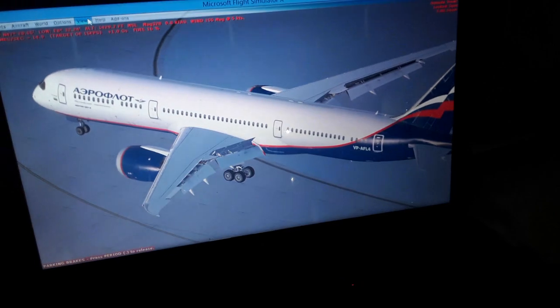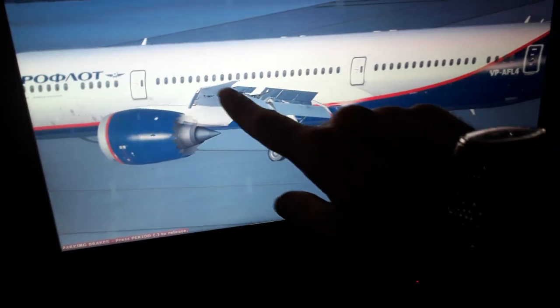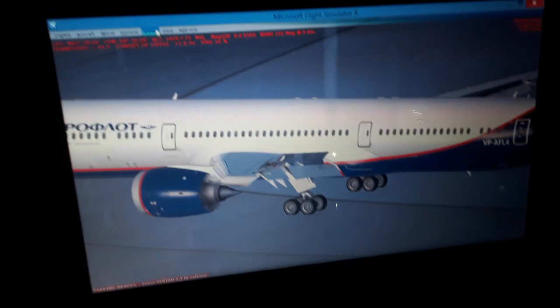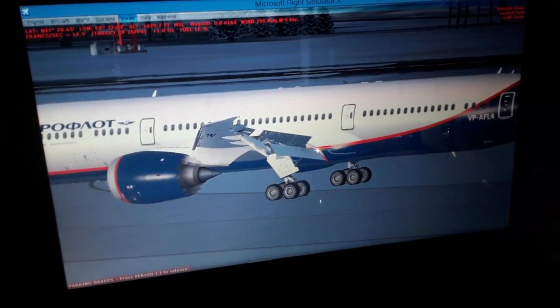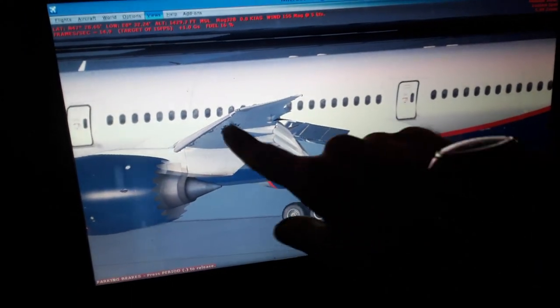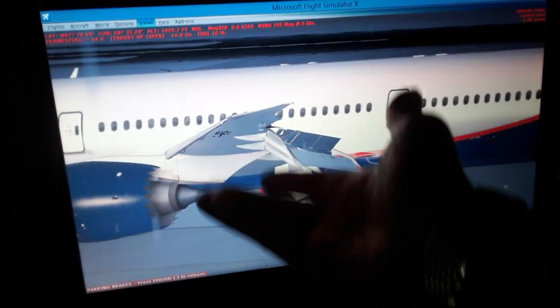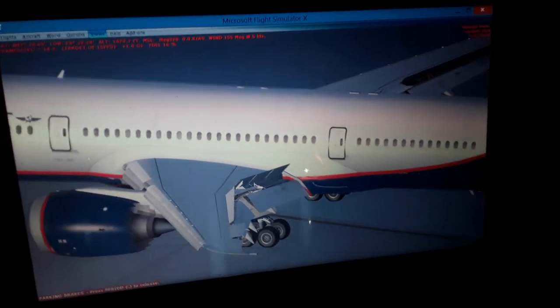You can see also that the bottom surface of the wings is flatter, using Bernoulli's theory of fluids. Also we have the extended flap, and when we fly the aircraft will have an angle of attack that is positive most of the time. So then we're going to have a lower airspeed below the wings. Using Bernoulli's theory of fluids, this gives us higher pressure below the wings, which pressurizes the wings and lifts the weight up into the air.